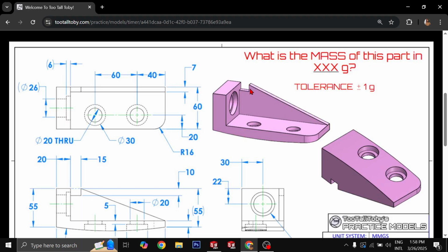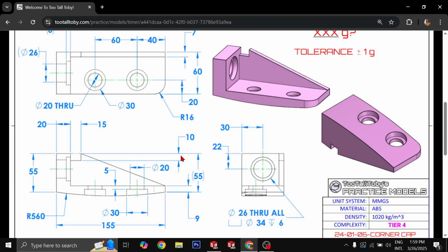Then we can draw this part right here, selecting that face as a sketch plane, and extrude it up to 7 millimeters. Then we can draw these 2 holes and the fillet, and we are done. So the first feature is this part right here. Second feature will be this rib like structure. Third feature will be the fillet, and fourth and fifth features will be these 2 counterbore holes. Simple as that. So it will take 5 features for us.